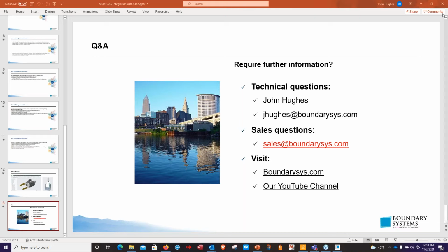And then this is just that process: as long as the name has not changed, if you update the SolidWorks assembly or one of the SolidWorks parts in that assembly, and then you go to update this, it'll point out those notifications. It'll recognize that there was a change and identify it. There's a way to do it automatically, but in this case, we just wanted to show the power of it to tell you that changes were made. There were updates to some component or model in there since the last time you looked at it, and you need to be aware of it and then implement the changes to fix that.